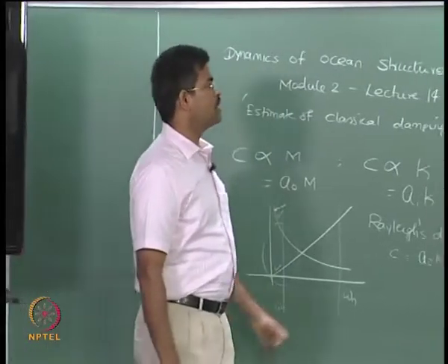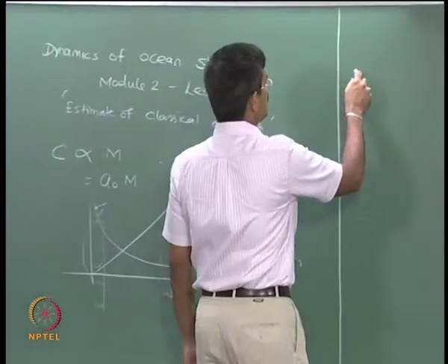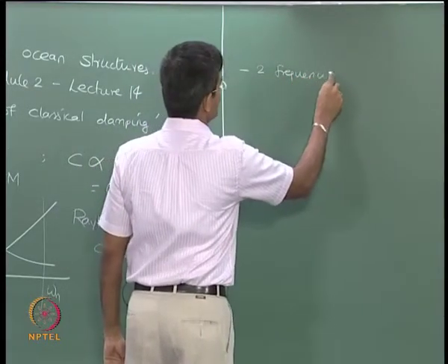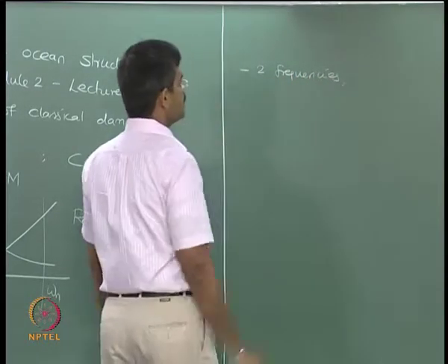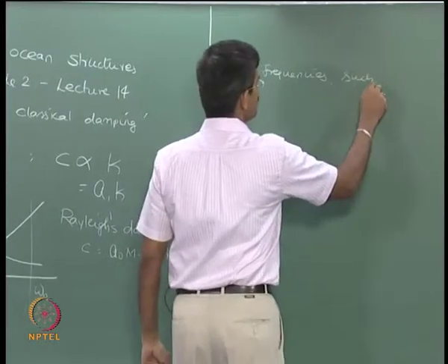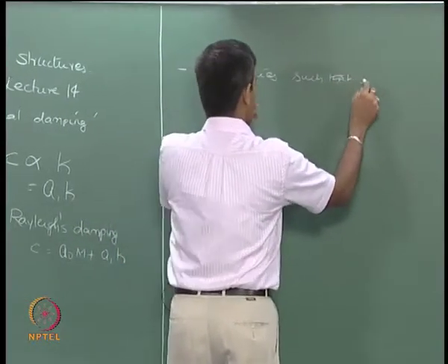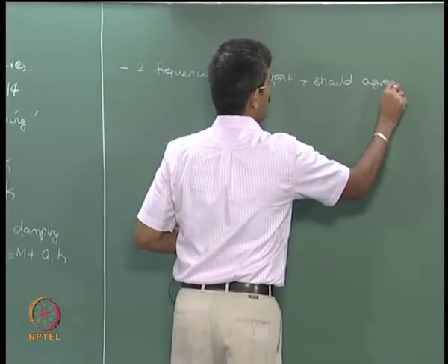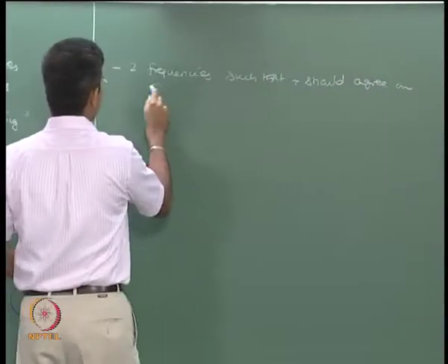Now, the difficulty with Rayleigh is you must select two frequencies such that these frequencies agree on the same damping ratio.